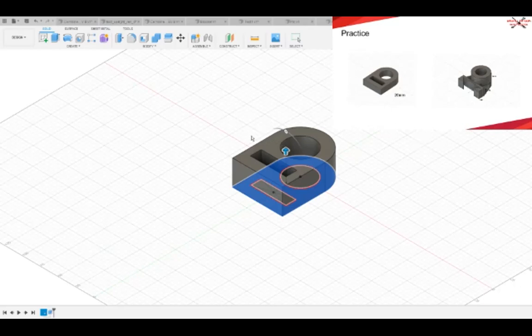If this was, say, a more complex sketch, you could extrude it up to an already existing surface, and it could stop there, or it could just extrude as far as you need to, which is only more applicable to cuts. You would never want to have an infinite extrusion, because then that part is, in the most literal sense, infinitely long. But infinitely long cuts are applicable, because that means it just passes through all solid geometry.